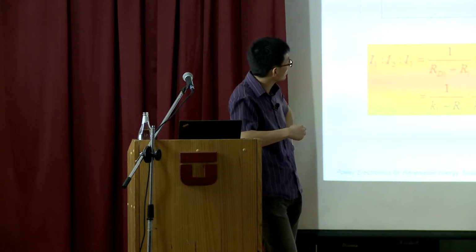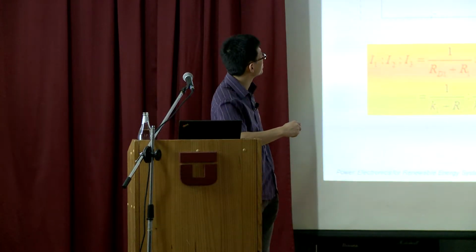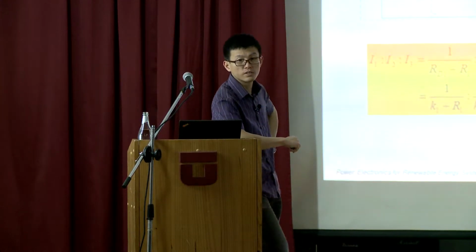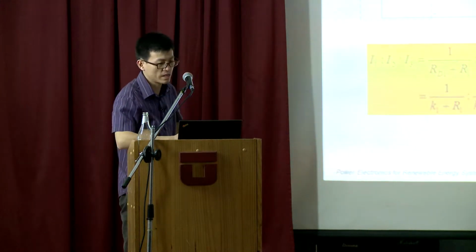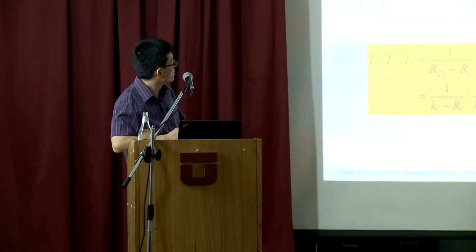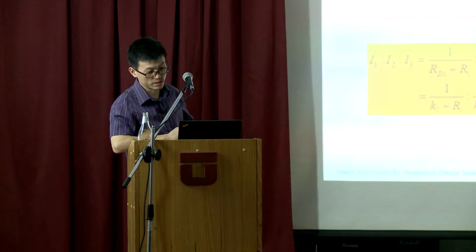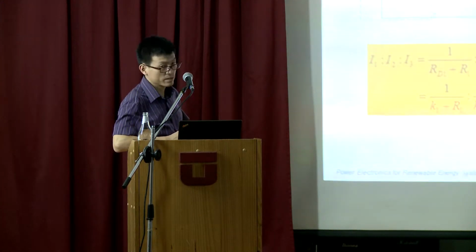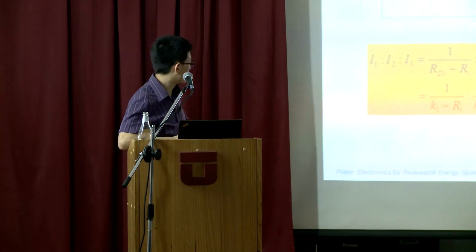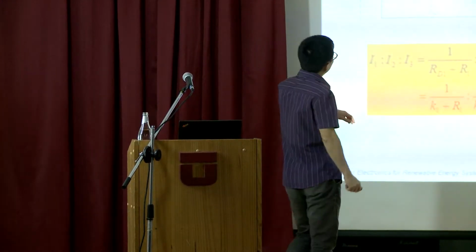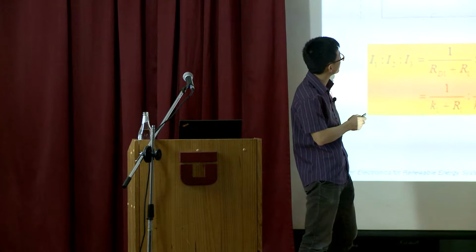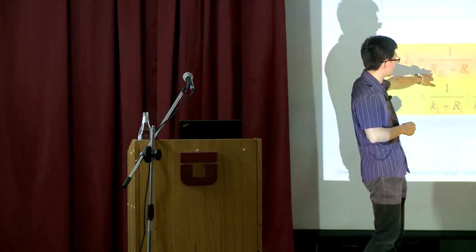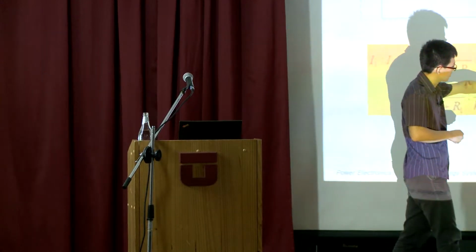This is actually what we're pretty familiar with from yesterday. The voltage mode droop is essentially voltage connected to a resistor, a virtual resistance, which we talked about yesterday as well. But the main problem for this voltage mode droop is the line impedance. When I design the power sharing, I design the droops RD1, RD2, RD3. I want the power sharing to exactly follow: I1, I2, I3 should be equal to 1 over RD1, 1 over RD2, and 1 over RD3.